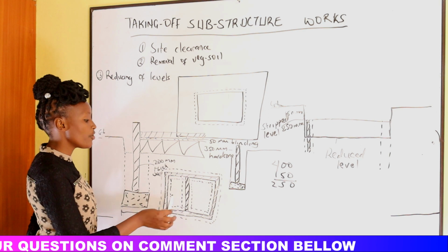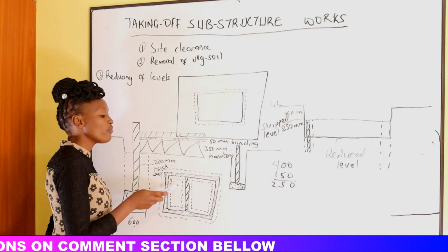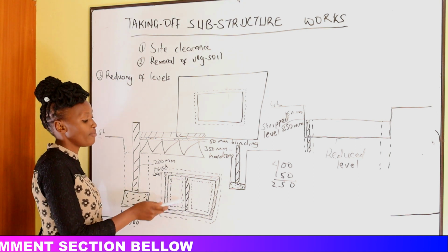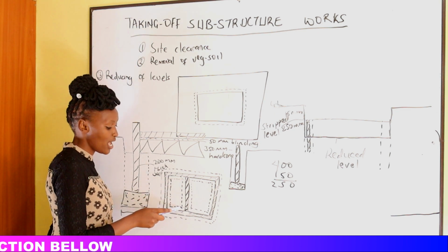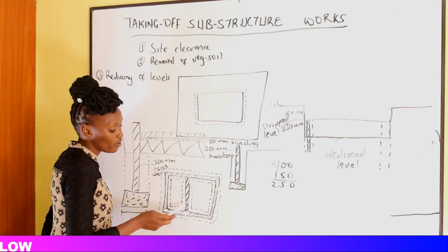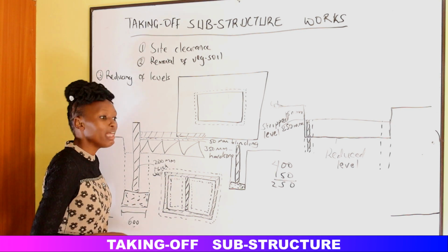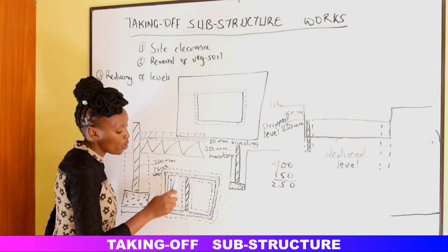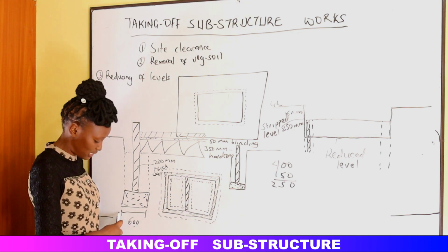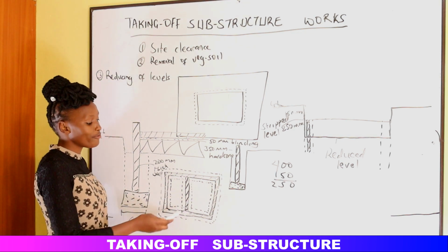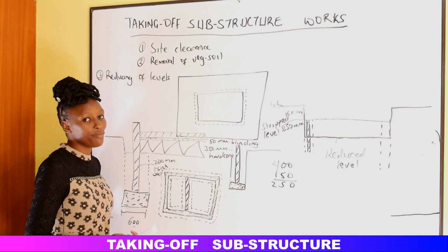Alright? So the volume of soil for the excavation of the trench for the internal wall shall be the length from here to here, which is the total length of wall to wall, deducting the spread here and the spread here. Then we multiply by the width of the trench, like this one, 600. Normally, for the internal walls, they are usually smaller, maybe 450.